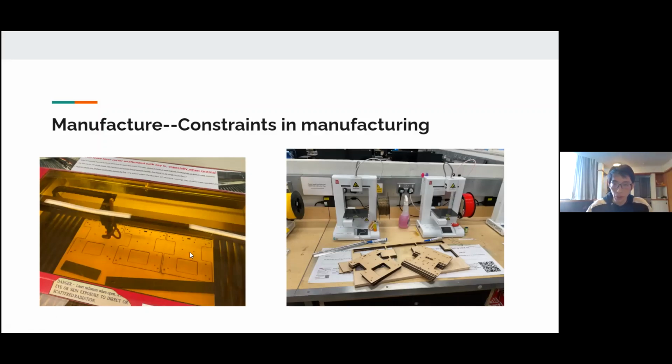The design used to be the bottom chassis, 200 times 200 mil, but because each of those sheets is 300 times 600 mil, if you try to cut 200 times 200, you can't really fit 3 of them. That's why I changed it to 190 times 200, just to make sure I don't waste too much material. Otherwise, there will be an L shape wasted.